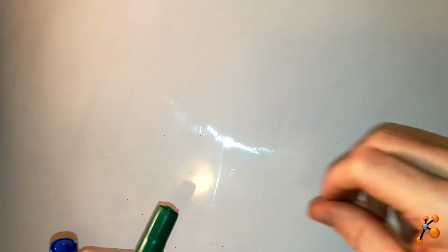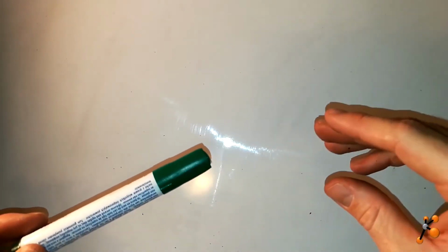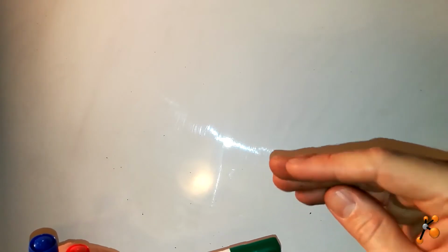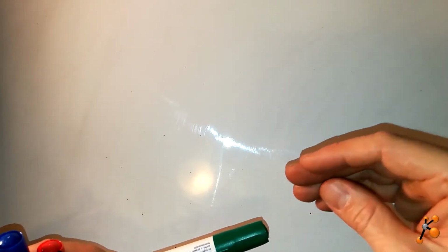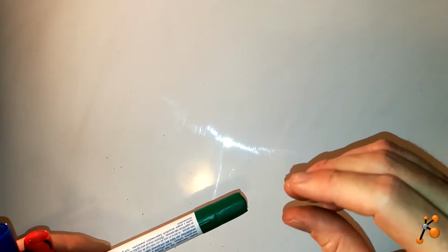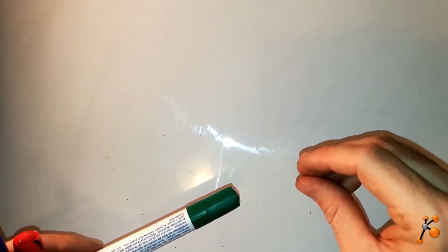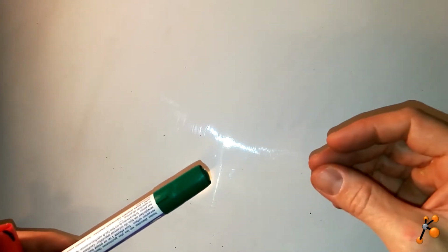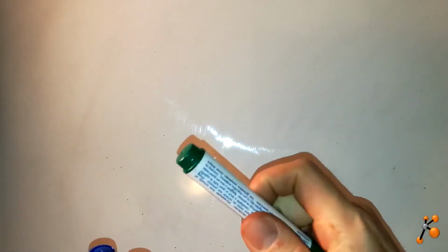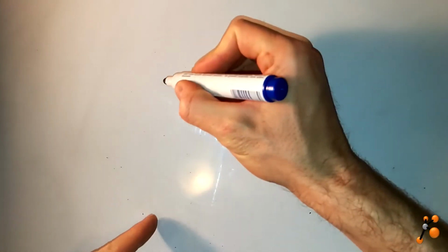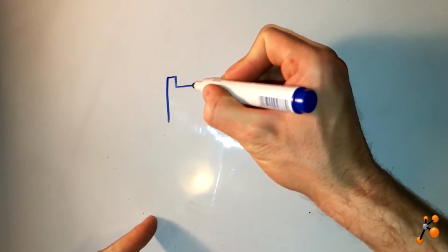And this system will not use sophisticated optics, but just a simple LED. So first, I think this is just some idea, you have to define your project, so what you want to read. In my case, I want to read GFP. So I will need the right LEDs to excite the GFP at the right wavelength. If I have to use RFP, it will be different. So in my case, I try to get a blue LED. So I ordered a blue LED.